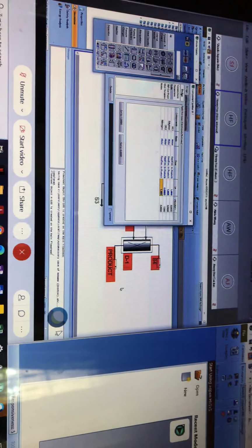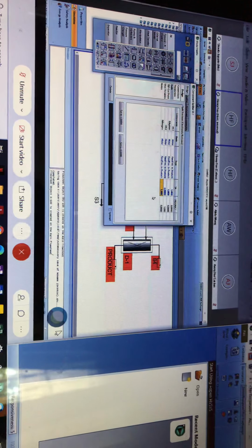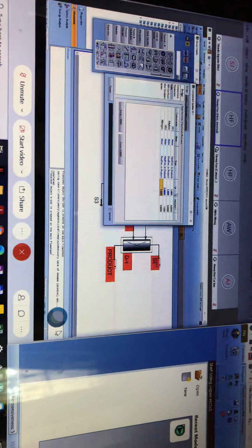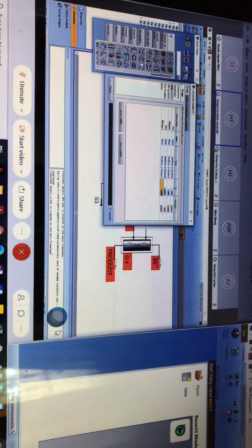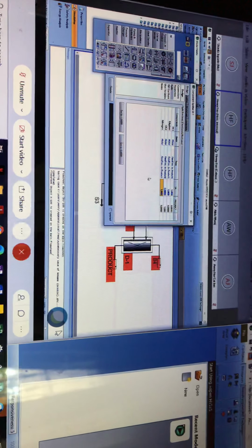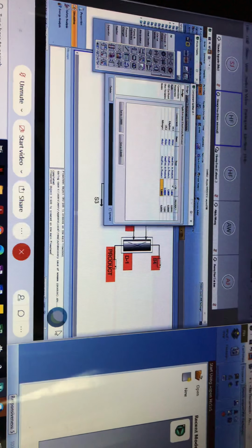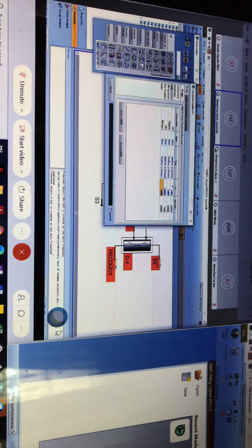So your product stream should only consist of products, meaning pure products. In this case, we are assuming it has 100% separation. So we only need to define one for S4. Then the software will automatically help you to calculate the balance of it, meaning the value for the product stream.